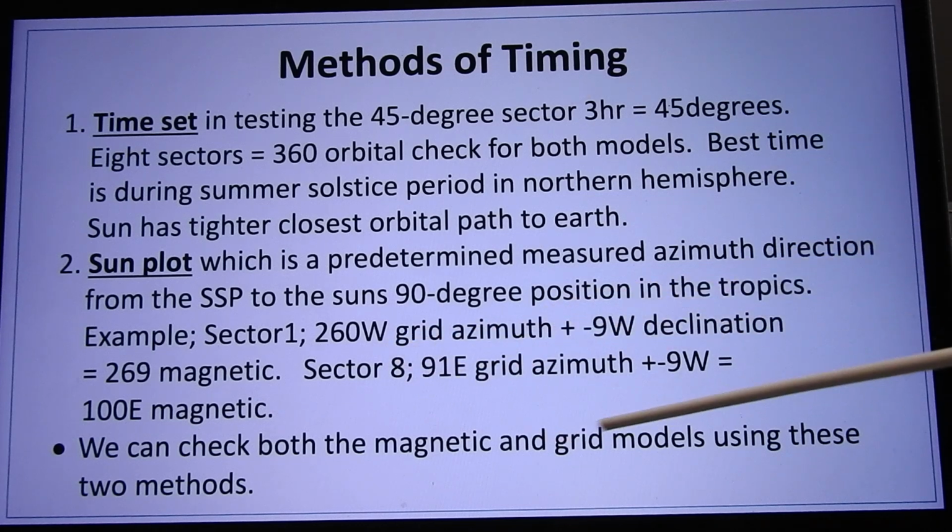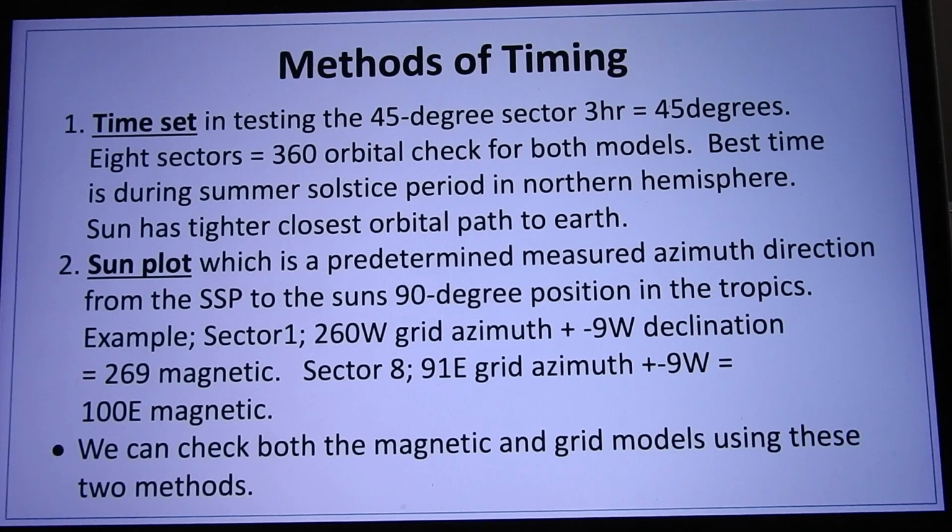And the second part is we can check the grid. We can check the grid on both models, both the flat Earth model and the globe model. The sun is very, very accurate. And again, military science has been using it for decades for positioning. I've done it using artillery for positioning and then bumping it against another methodology. Very, very little difference. 99.9% of the time you're going to bump within 1 or 2 mils, using grid magnetic, and again, that's how we can tell there's little or no refraction, less than 1/3 of a degree.